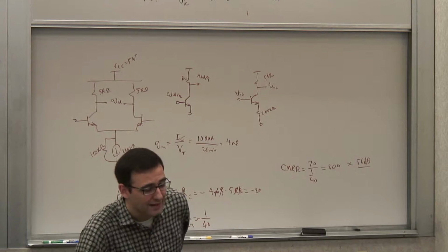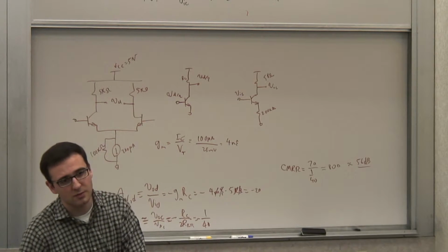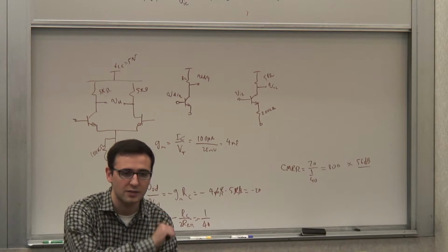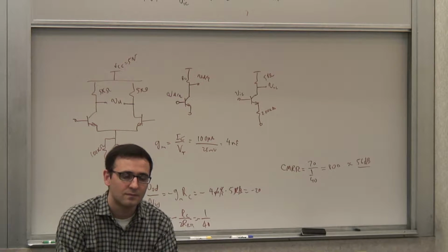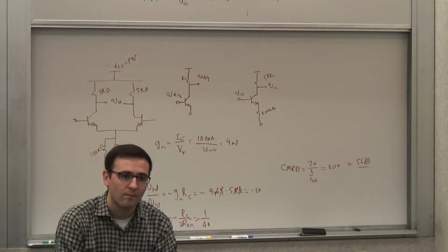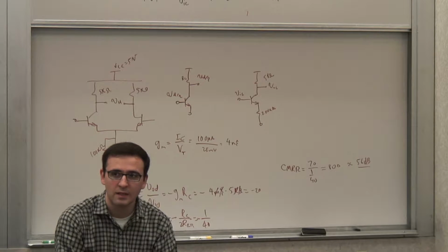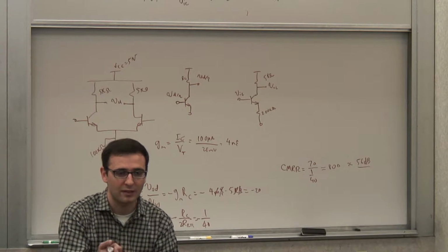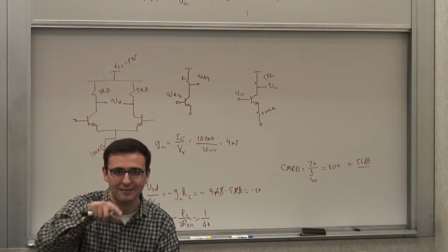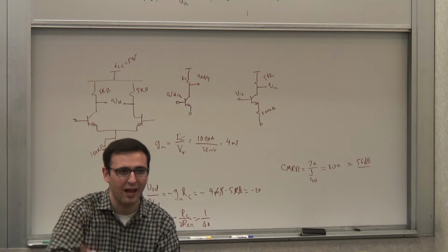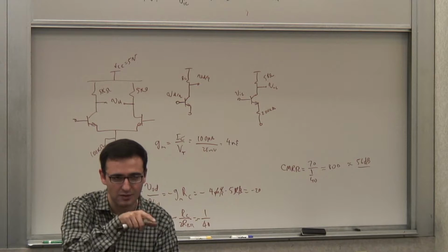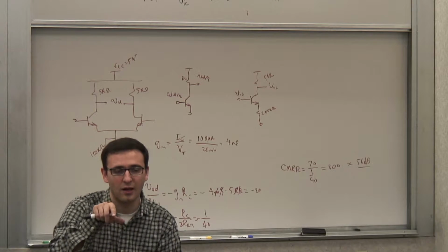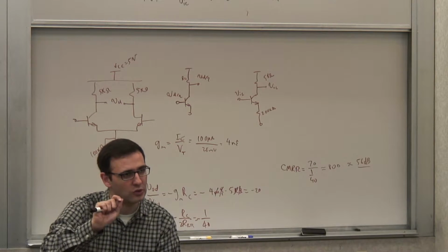But remember, an input voltage in the range of 0.1 volts corresponds to an output voltage in what range for this amplifier? 2 volts, right? Since you have a relatively good gain, of course the input signal has to be small. It doesn't mean that you can't make large signals on the output. The only thing is that to make those large signals without major distortion, you need to use a small input signal.